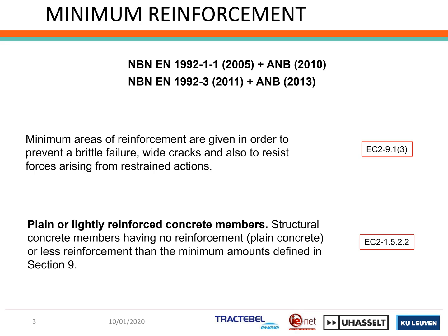Plainly or lightly reinforced concrete members. These are structural concrete members having no reinforcement or less reinforcement than the minimum reinforcement. This means that if in a concrete member you do not put the minimum reinforcement as required, then this member should be regarded as plain concrete.